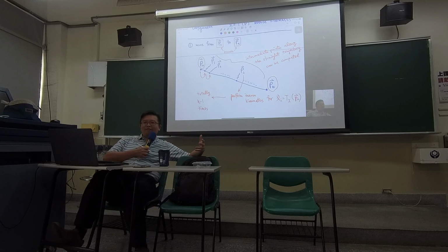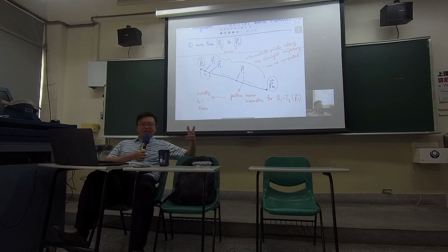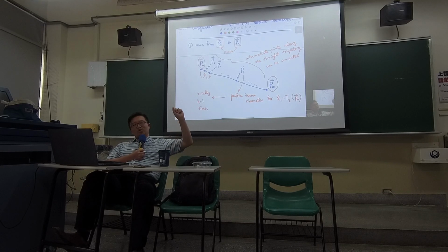So usually for controllers, if you assign a linear motion, it actually cuts this straight line into so many small points and performs a lot of inverse kinematics for each point. So the controller, the computer, needs a little time to perform inverse kinematics. Okay?